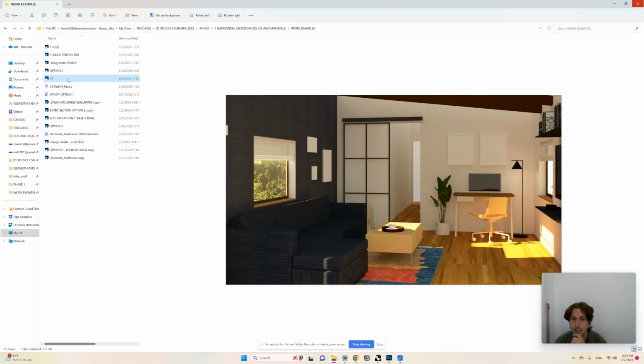This is an addition in California, and one thing that was important here was how the light enters the space. It's very bright, so we needed to make sure that we weren't going to have problems with glare on the screen here or the television here for either relaxing or for working. Rhino is really good for examining the sun, and you can set the location of your project and see exactly how sunlight will enter the space.